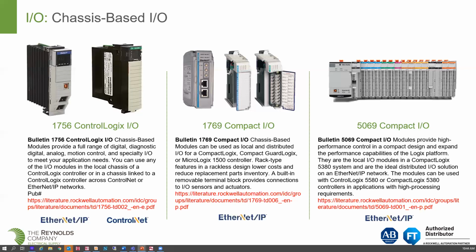So this will work with the 5380 and the 5580 CompactLogix, but you cannot use one of the older gen processors such as a ControlLogix L7 or the 1769 CompactLogix. Those do require a quad core processor, so that's one reason why we can't use this. Now, we'll go into a little more detail on what makes this a really nice IO shortly. We're going to come back and revisit this one.